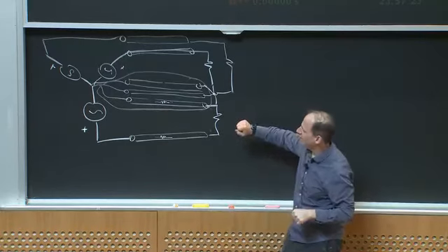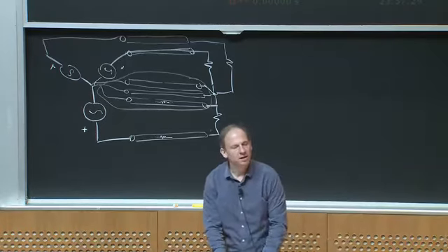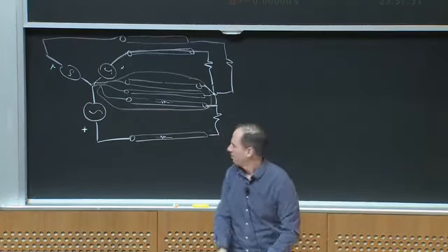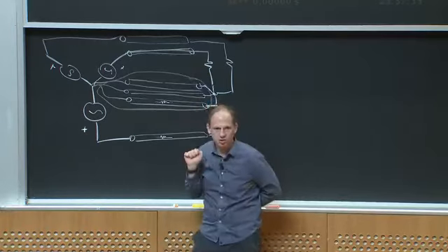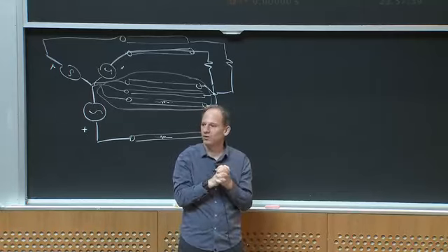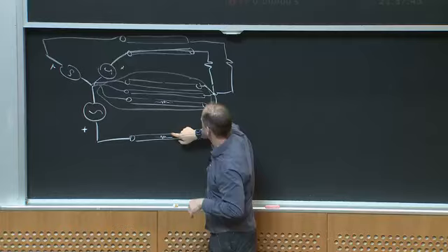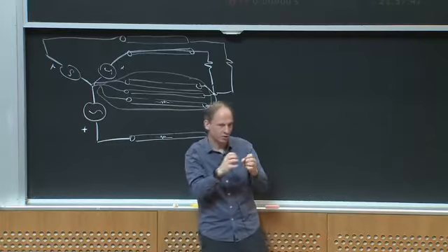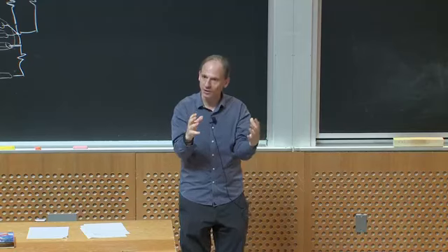While I haven't calculated it for you yet, the voltage rating between this phase and this phase is actually the square root of 3 Vs, okay? So you need a little bit more insulation if you're going to put this conductor right next to this conductor than if you put this conductor next to the ground, right? But if I cared about insulation, I could just turn down the voltage, right?